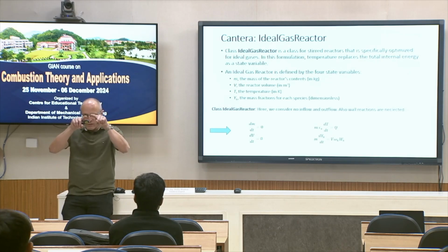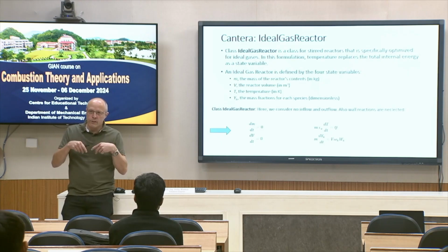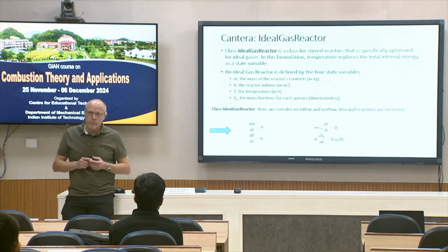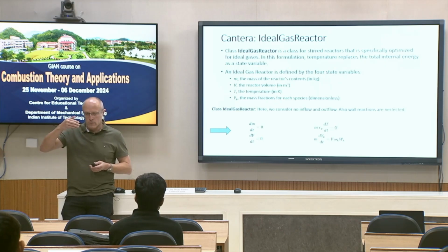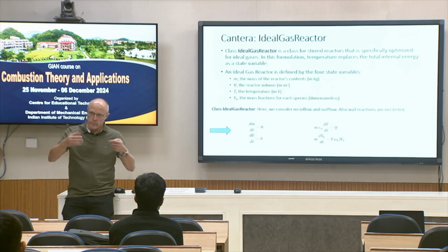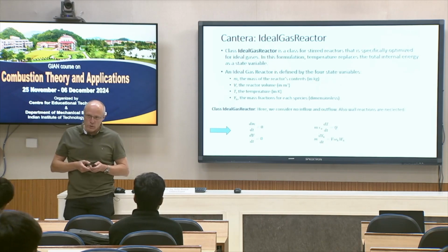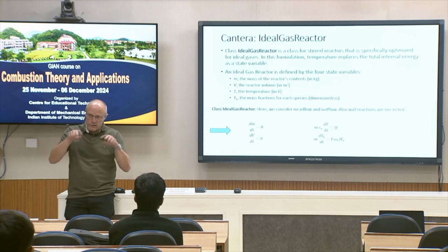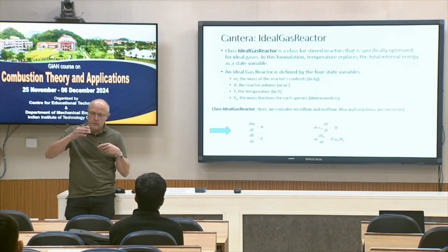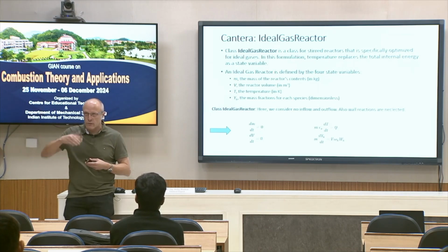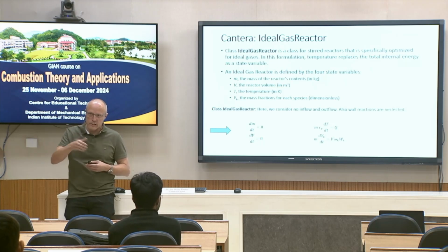That means you have a closed system filled by your homogeneous gas mixture, at a given pressure and temperature, and then you solve your set of governing equations. In the case of constant volume, volume is constant, temperature increases, the number of moles is changing, so pressure has to change when we look at the ideal gas law.